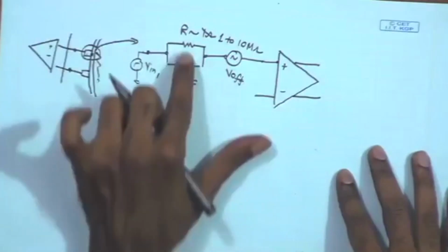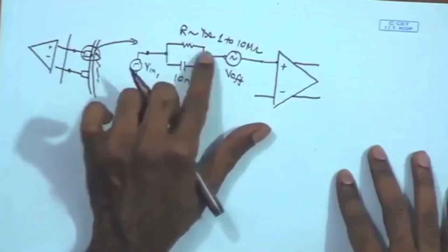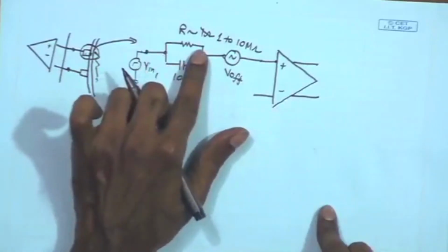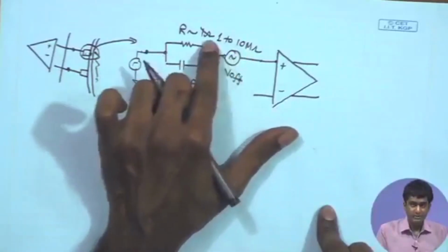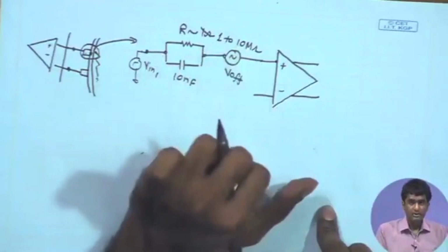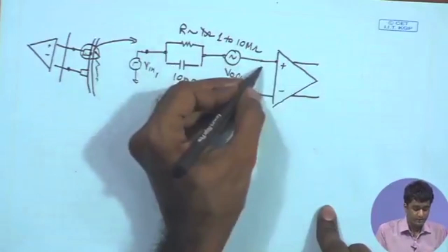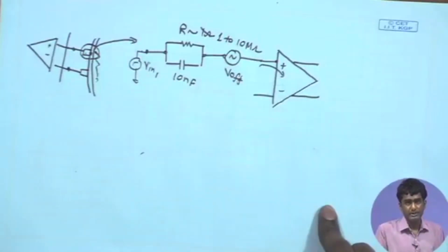Now, here if we look at the electrode characteristics, the R of the electrode is almost acting like a source resistance, and this is pretty large, it can be 10 mega ohm. As a result, if we want this minute signal to be amplified nicely, we would like to have the input impedance of our amplifier also to be pretty large, maybe larger than 10 mega ohms to few hundreds of mega ohms, and so on.